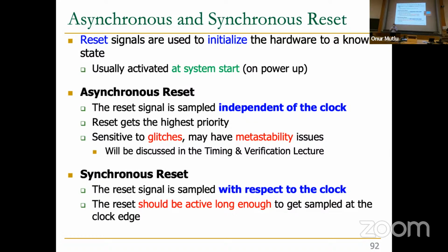Well, for example, I'm a user. I want to reset the computer. I press a button, and it's independent of the clock in a sense, right? Make sense? So you need some asynchrony to make sure that that reset button actually works in a computer, because the clock may not go from the rising edge to lowering. The clock may not take the rising edge or go from 0 to 1 when I'm pressing the button, right? I may not be able to capture that point in time. I need to press the button long enough to potentially capture that point, right? Okay, that's just for you to think about.